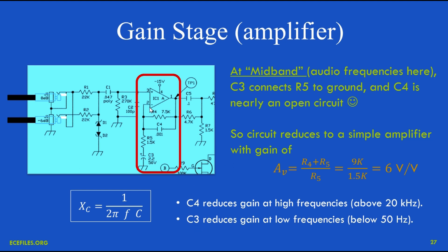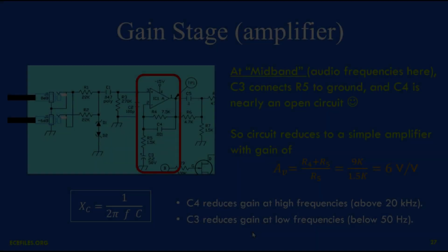One other reason for C3 is that this op-amp, as we'll see in maybe another episode in the future, has a little bit of bias current coming out here which goes through R3 and creates a DC offset. And if we amplify that, it could, well, it's not going to saturate the amp because when I calculated it for the device being used, it's only about 1 volt maximum here. And downstream circuits have AC coupling capacitors to block DC. And so I don't really know why C3 is here.